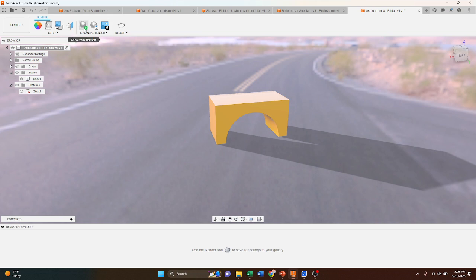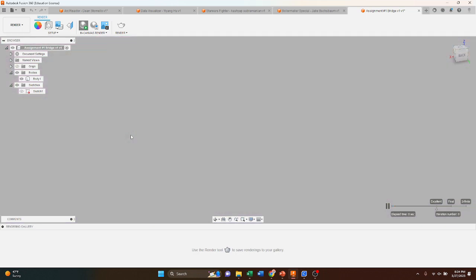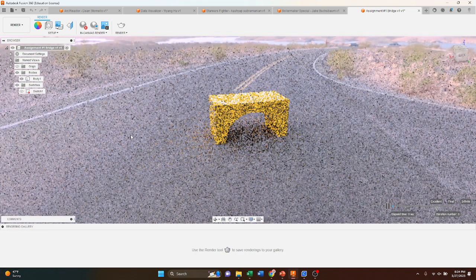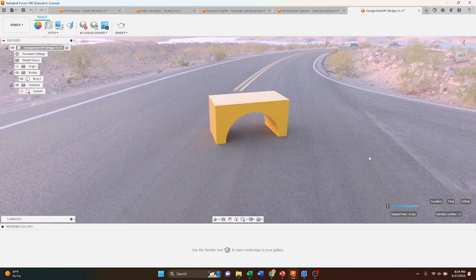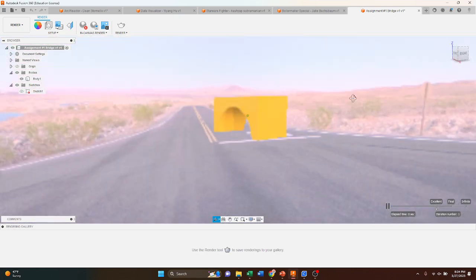So the rough draft button is this one right up here with the plus button, and you'll push it, and it'll slowly start to render the background. It'll do about 90% of the final draft. So as you can see, right, it's slowly getting better and better quality. Whenever we go to do our final render, again, this is what it's going to look like. If you're not happy with it, again, it is a rough draft, so you can move it around. It's going to break it, but then as soon as you let go, it'll start rendering again.